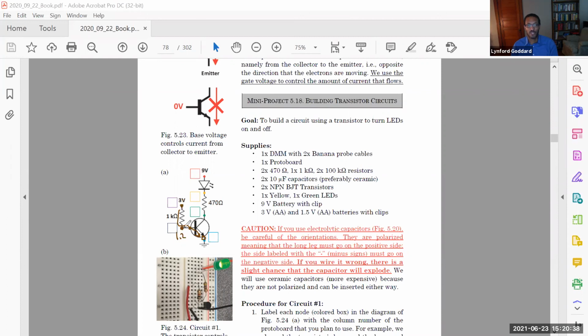So very good question. In the case that I have a voltage signal, like if instead of 3 volts, this were 1.5 volts, then this point would still be at 0.8 volts. And so I would drop 0.7 volts across the 1 kilo ohm, and I'd get 0.7 milliamps of current flowing into the base. But that's still enough because the voltage I'm applying is still greater than 0.8. It's still enough to turn on the transistor.